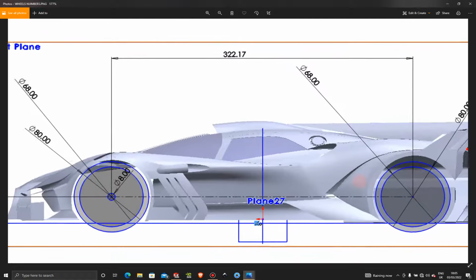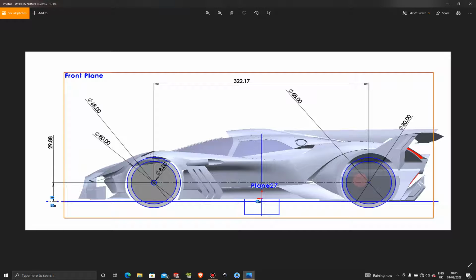Because what we're going to do is create the wheels and tires in a brand new sketch, because I wanted these to be two separate parts, because once we jump over to assembly, I want these wheels to be able to spin, and of course in the front I want to be able to spin and also turn left and right, which we will create the mechanical structure and the mechanical mates for, so we can add some animations on that one as well. So if you want to take a picture of this and then use these measurements, you can, but I'm pretty sure you have different measurements on yours.